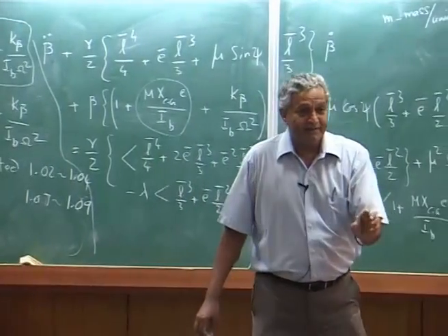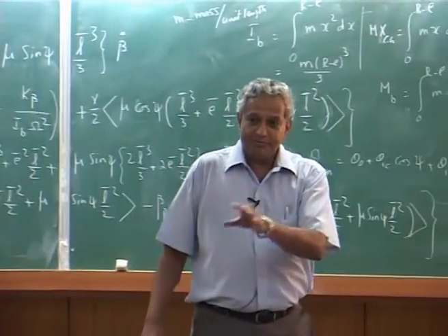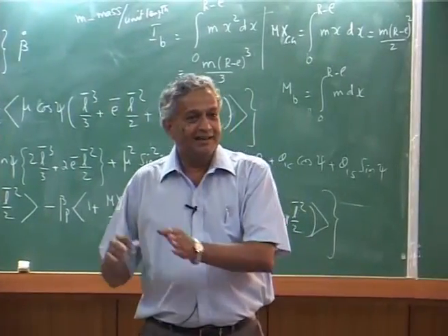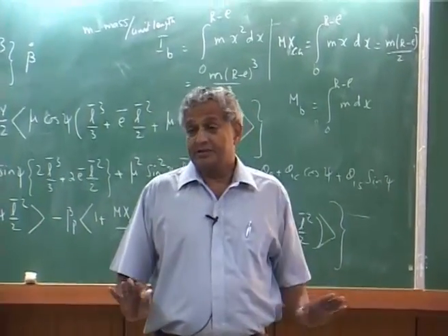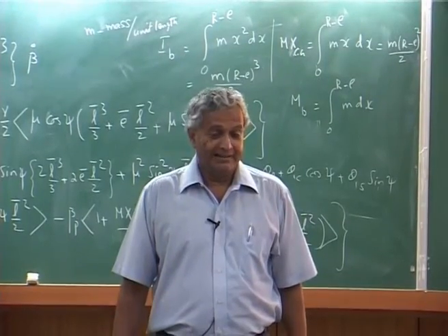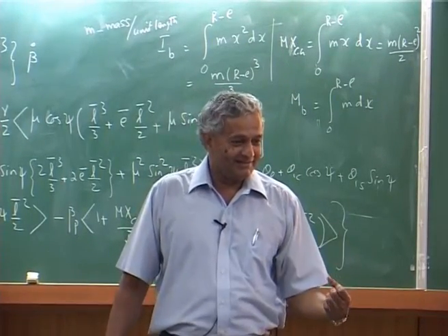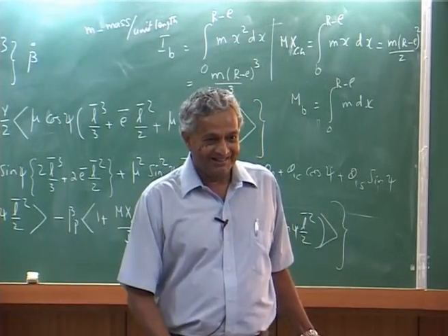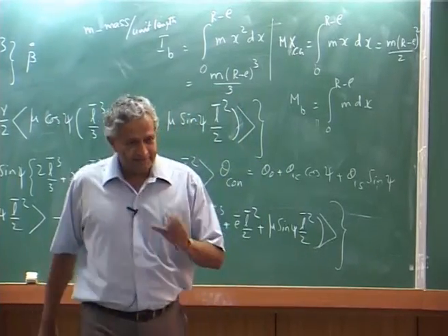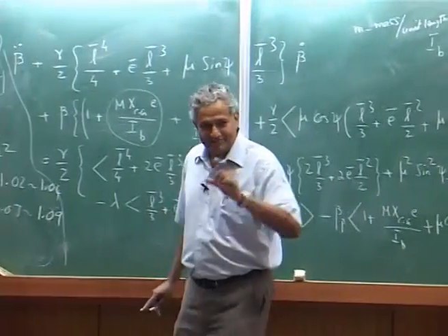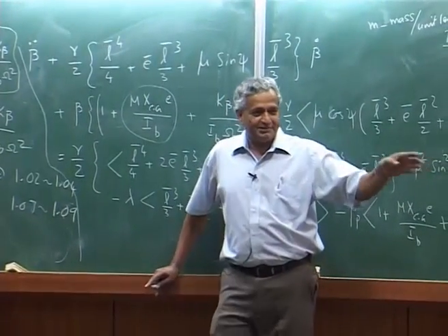So, you will find the problems will be, if it is hingeless, your vibratory loads also are higher. So, you get a control moment high, but your vibration is also high. Now, what is the choice? So, this is where every parameter, everything, there is a plus point, there is a minus point.